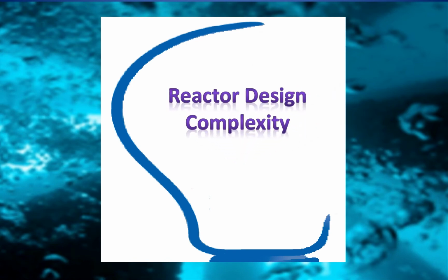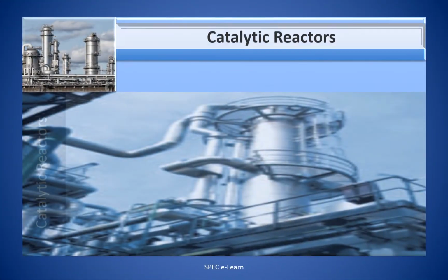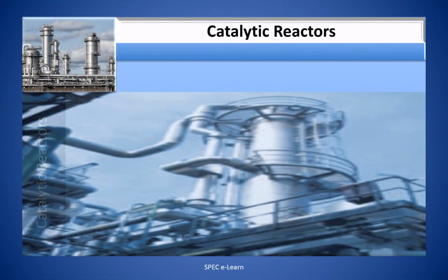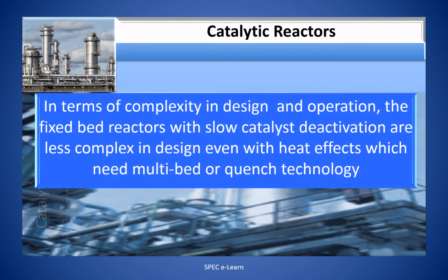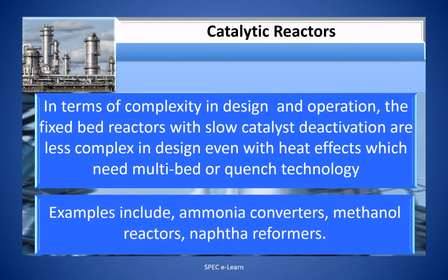Reactor design complexity. In terms of complexity in design and operation, the fixed bed reactors with slow catalyst deactivation are less complex in design, even with heat effects, with multi-bed or quench technology. Examples include ammonia converters, methanol reactors, and naphtha reformers.